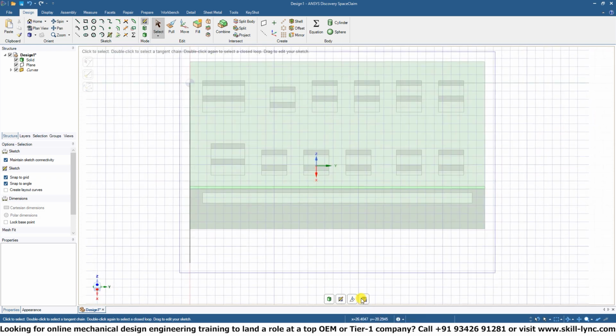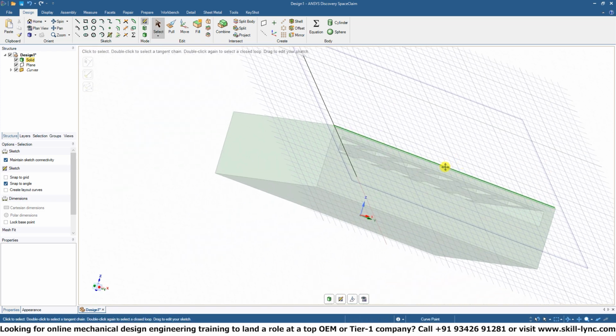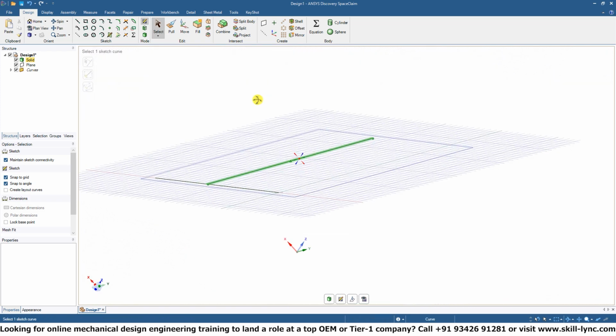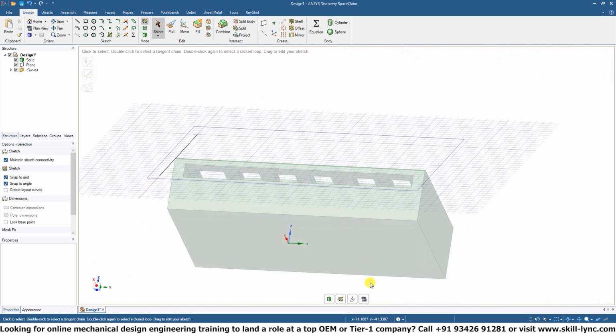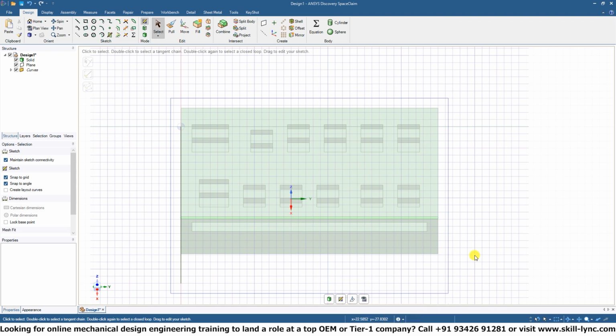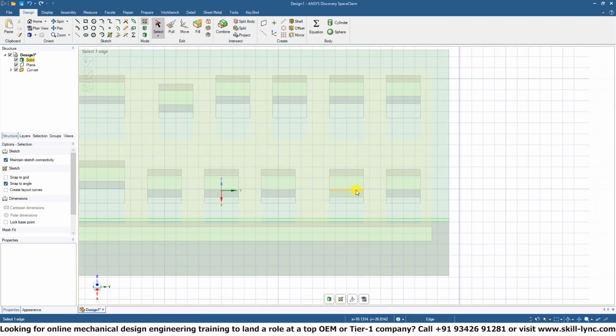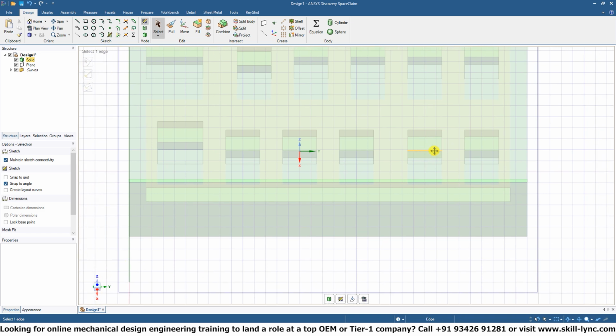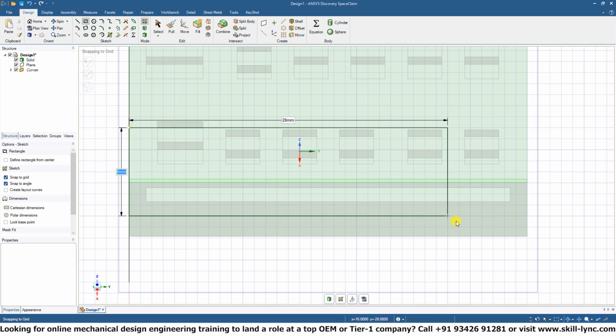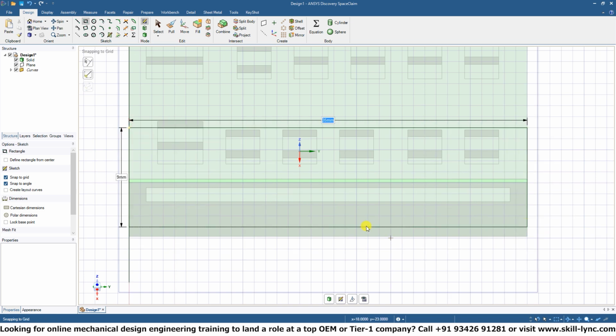this is another quick tip. Obviously, instead of fumbling around, rotating, moving about, if you just want to face the plane that you're sketching on, if you select this button over here, plane view, or quick key V for view, you would be directed perpendicular to the plane that you are sketching on. As an example, we're now sketching on this diagonal plane.